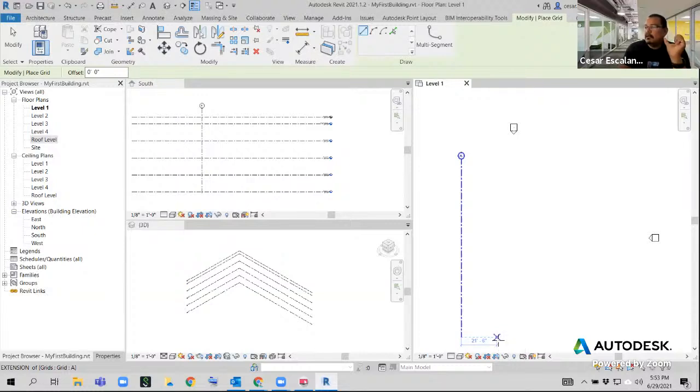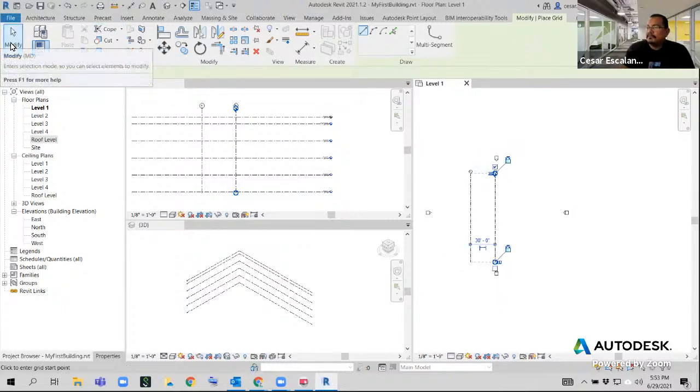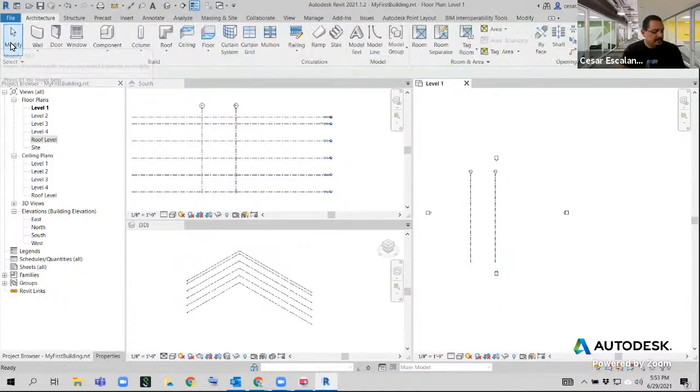They are dimensional constraints to the extension of an endpoint of an object. For example, if I want this to be 30 foot away from this endpoint, all you need to do is navigate to the end of here and then scroll to the right. And when you hit 30, that's where you do your first click and then snap 90 degrees. And that's going to be your B. And there you go. Escape to cancel.